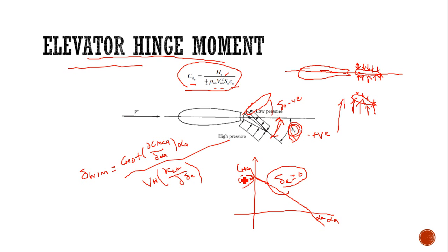So the CM0 will be here, and we have the trim angle of attack here. When the elevator is deflected to some positive angle, the CM value will also move towards some new value. That is, we will be having a new moment.